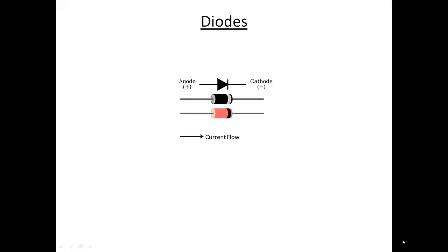The voltage drop across the diode can vary from 0.2 to 1.2 volts depending on the type of diode. The most common voltage drop associated with a diode is about 0.55 to 0.65 volts. You'll need to take the voltage drop into consideration whenever you're using a diode in a circuit.